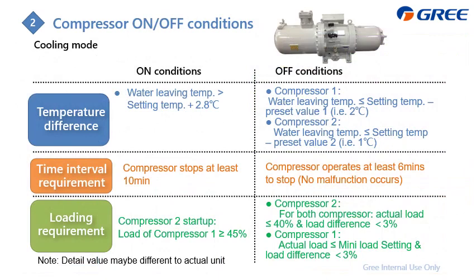This slide displays the compressor turn on and turn off conditions, including three conditions. For example, in cooling, first is the temperature, which is the water leaving temperature. It should be higher than the setting temperature plus 2.8 degrees. Then this is clear, we allow it to turn on.